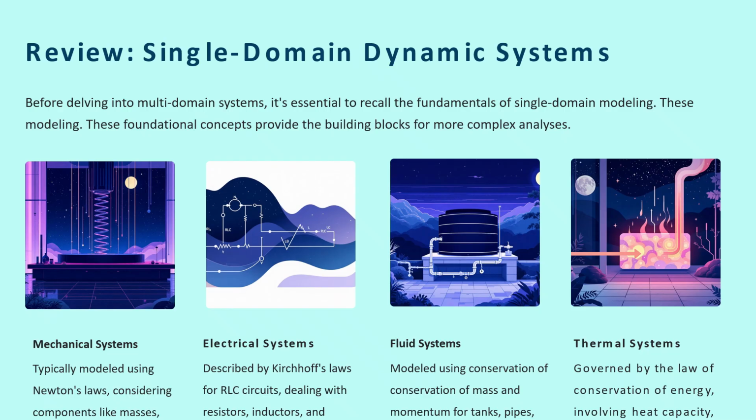Fluid systems are typically modeled using conservation of mass and momentum, such as fluid tanks, pipes, and flow resistance. Similarly, thermal systems are governed by the conservation of energy, where thermal capacitance, conduction, and convection determine temperature dynamics. Each of these systems already follows a well-defined dynamic law. The key idea in multi-domain modeling is that we do not redefine these laws. Instead, we connect these existing models through energy exchange and power flow, allowing us to analyze complex systems as an integrated whole rather than as isolated components.